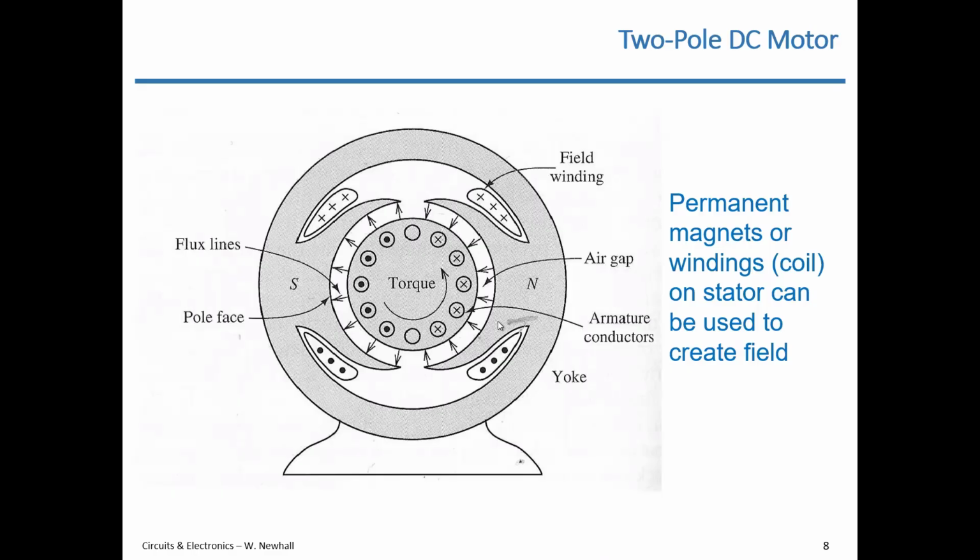And so imagine a coil of wire running front to back and along these slots here, creating that magnetic field. On the left side, you have the same thing, current going in at the top, out at the bottom. Okay, with the way these coils are oriented, you'd have a south pole on the left, north pole on the right, just like you'd have with permanent magnets, and then you would have an electric motor here.